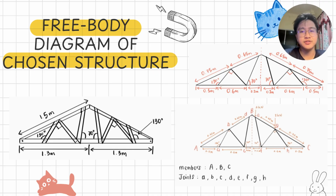And the next one is the free body diagram of the chosen structure. The original roof structure is simplified into a truss system to make analysis easier, and all members are represented as straight lines connected by pin joints. The joints are labeled from A to H to clearly identify each connection point.